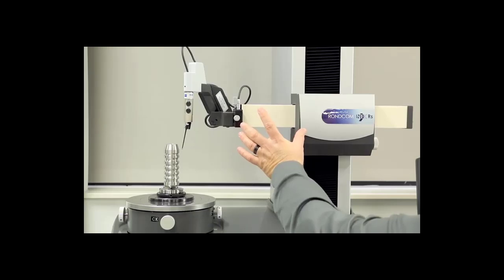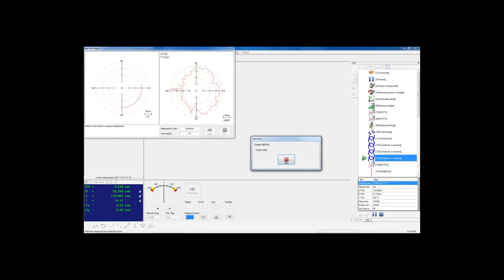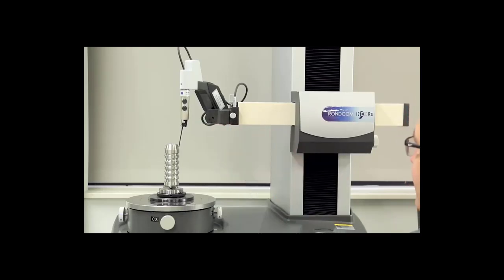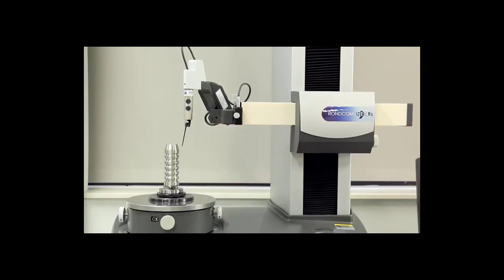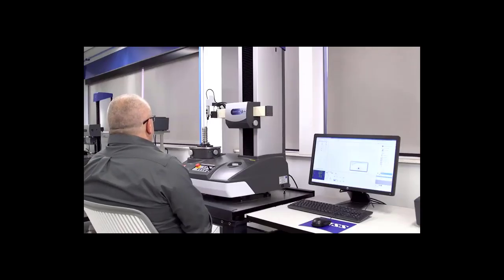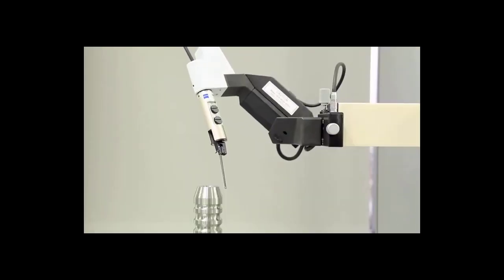We have the ability for R-axis tracking, so as this machine moves forward to take the measurement, as you look between your indicator for your stylus and the motion, you can actually see the R-axis moving to follow to keep your stylus in the center of the range. On the next 300 model, we also have the ability to rotate the stylus to keep it normal to the surface with a motorized CNC head.